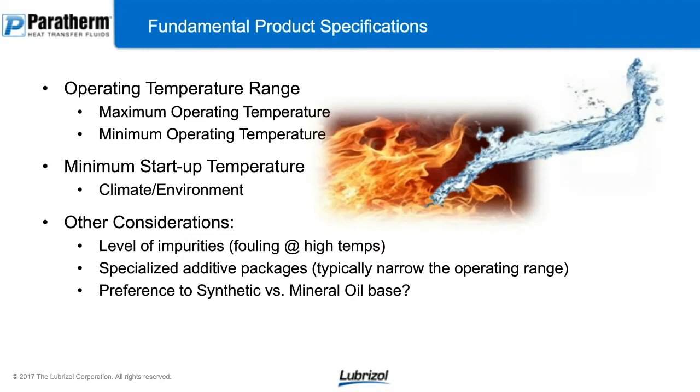You want to look for a fluid that, if you need it, will have a specialized additive package, just keeping in mind that those typically narrow the operating range and increase the viscosity of the fluid. And then obviously, if you have a preference for synthetic over mineral oil, you're going to want to look into that a little further to make sure your fluid actually meets those criteria.